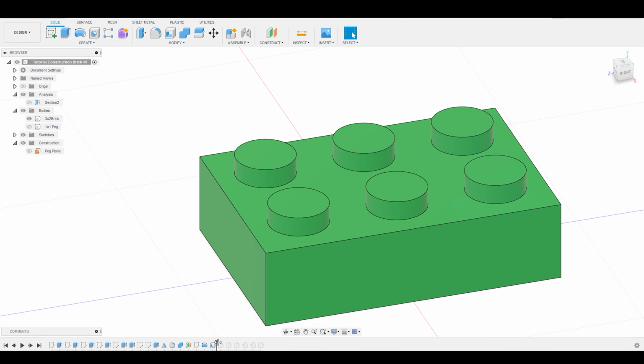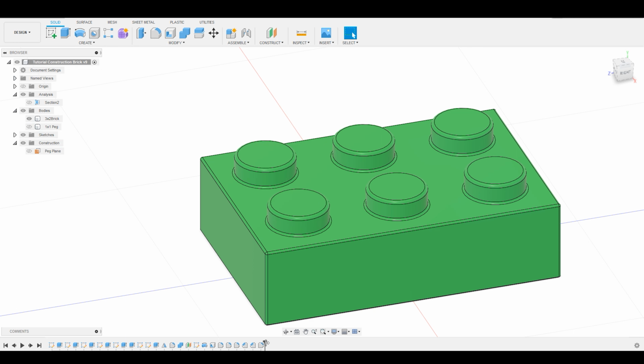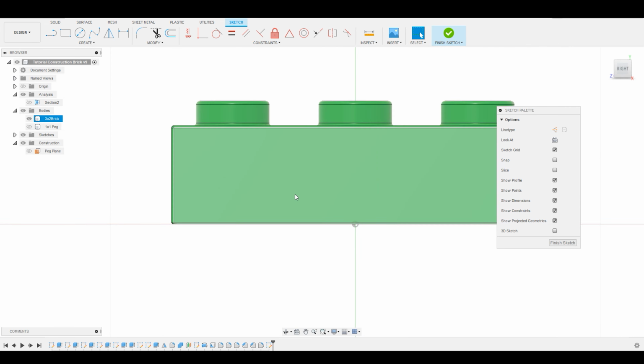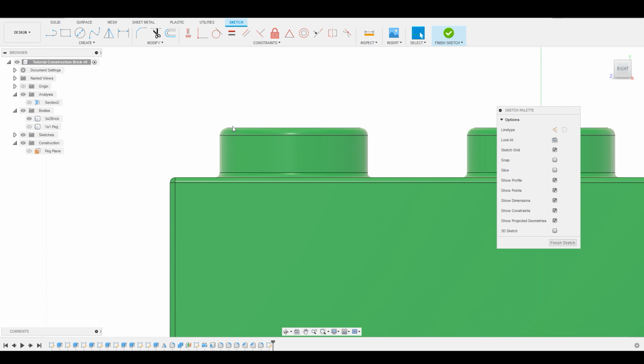Now, for the sake of this example, I'm actually going to slide forward to the end of our timeline here to recapture these fillets and radiuses, because now I do want to show you something about these fillets and radiuses. So I'm going to use this same peg plane, and I'm going to create a new sketch. All right. Now, for this example, because I want to hollow out the inside of this peg using this final shape, I want to just copy this geometry.